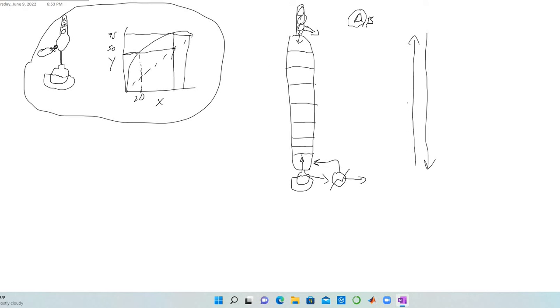To reiterate, this is the vapor line, and this is the liquid. As the vapor's going up, the more volatile component is going to leave the liquid and go to the vapor. But that energy needs to come from somewhere, and that somewhere is going to come from the less volatile component in the vapor phase condensing and entering the liquid phase as they pass by each other.